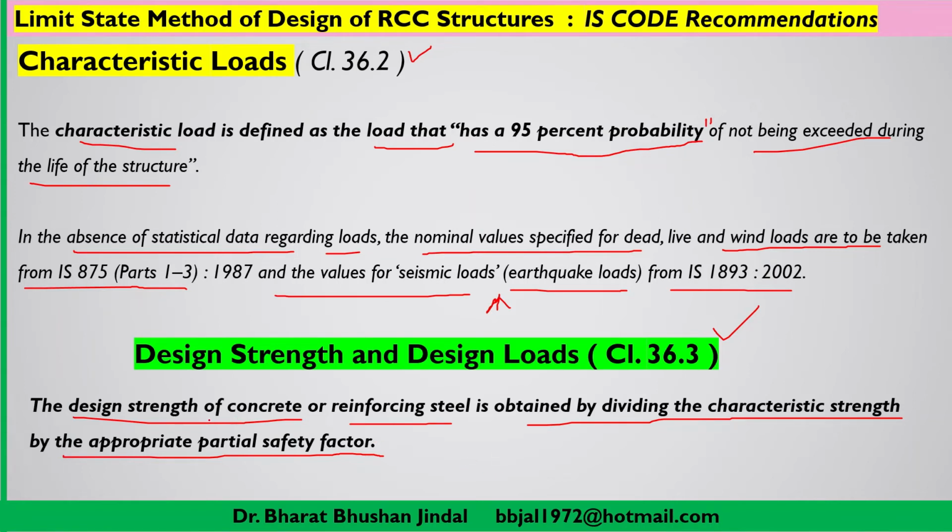So when you have to find out the design strength of any material, what you have to do is just take the value of characteristic strength of that material and divide by the appropriate partial safety factor, by applying various considerations which we will discuss in the coming lectures.